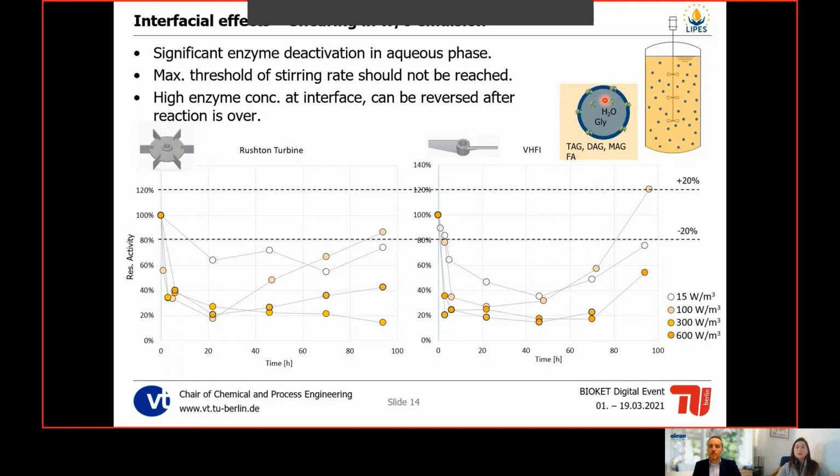With immobilized enzyme, the mass transfer from the oil phase, which has a higher viscosity, is lower, because if you immobilize an enzyme on a structure, the enzymes are usually hidden inside the porous structure, and the oil has to go into these pores. And if we are talking about high viscosity of oil, it's most likely that the mass transfer is hindered, that the substrate in the oil phase cannot reach the pores inside the immobilized enzyme. And that's why we are going with the free enzyme instead.